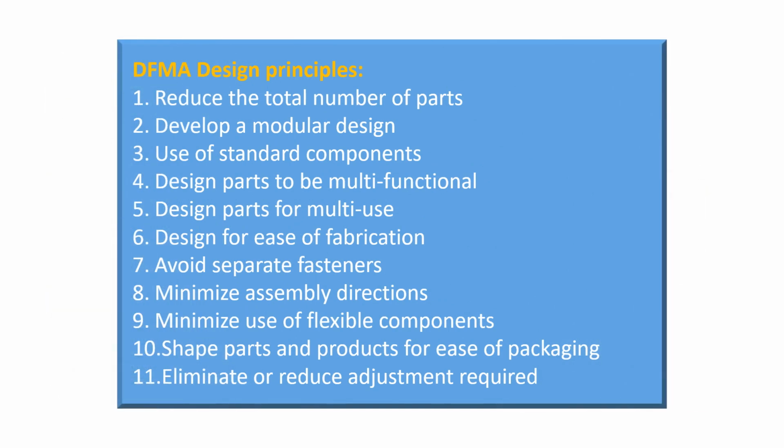When starting to think about the design of a product or part, it is worth considering what kind of manufacturing methods are utilized, and how their utilization affects the design. Design for manufacturing and assembly, DFMA, is a way to design products so that they are easy to manufacture and assemble. It is therefore a matter of optimizing the design of the product, assembly and part in order to make its manufacture and assembly cheaper and easier.